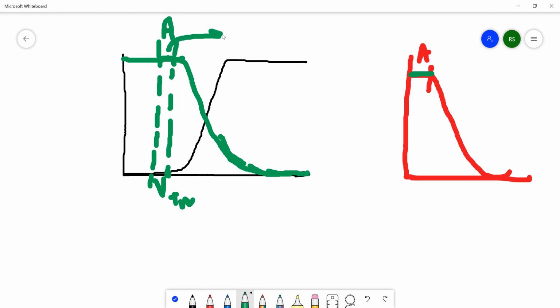This amount of time is called your contamination delay, tCD. For this amount of time, the output does not change. The output has not responded to the input. It continues to stay at the previous value. It could be high or it could be low. It doesn't mean that it happens only for a high value. This will happen for a low value also. But for some amount of time after the change of the input, you can consider this as inertia.